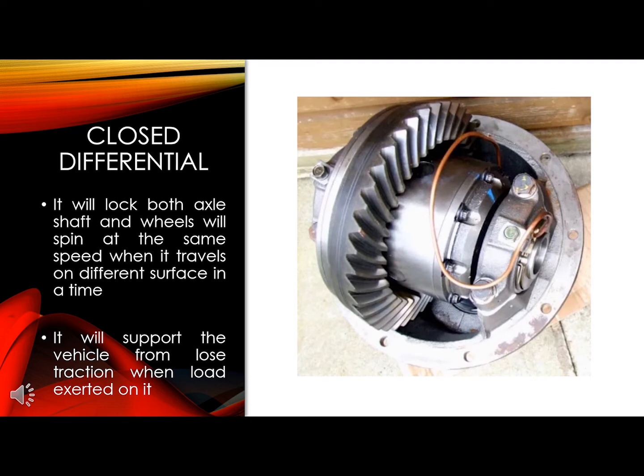When they drive on slippery road or uneven road surface, the differential will be locked on both sides and both tires will travel at the same speed to overcome the slip produced when driving on that type of surface.